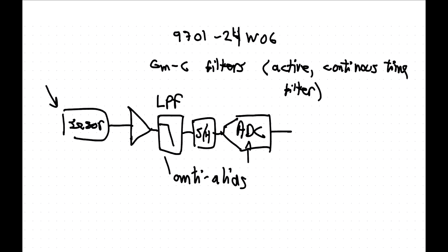Just a quick note: is the anti-aliasing built into all ADCs or microcontrollers? It should be. I've always wondered, because we never low-pass filter before sampling. Okay, so it's because it's built into the ADC. Yeah, it should be, like in an Arduino or USB device or something.